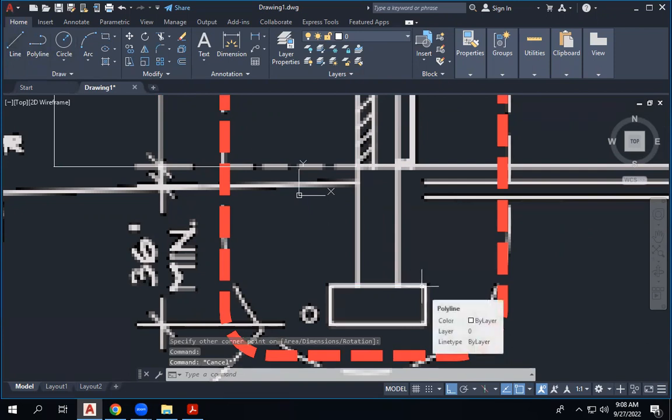To draw, we will do like this. We will make a few layers also before starting it. Then you have an idea where it cuts. The cut line will be thicker. So we will make a few layers with a few thicknesses. Then when you are drawing the main lines, you can use those layers to draw, without doing it in one layer. I'm just using this 0 layer.